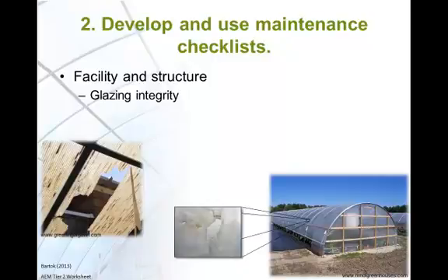Plastic film coverings require replacement at regular intervals. For example, Sunmaster infrared anti-condensate thermal greenhouse film has a 4-year lifespan. Consider anti-drip coating and UV coating. Check static pressure of double-layer air-inflated roofs and walls. Either over or under inflation can shorten film longevity.